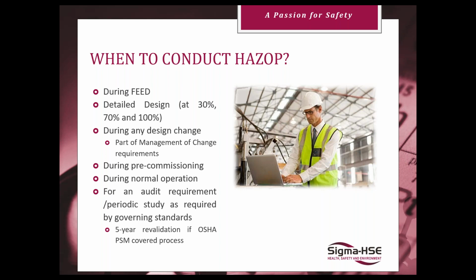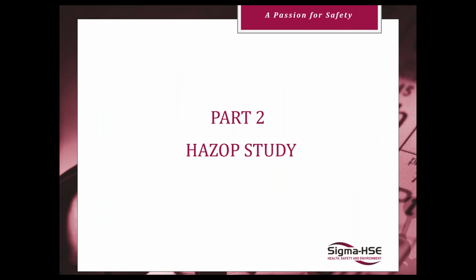Pre-commissioning activities, construction's completed, you're about to start up, perform a HAZOP on your commissioning activities to make sure your commissioning procedures make sense. Normal operation, audit requirement, periodic study is required by governing standards, 5-year revalidation if it's OSHA PSM covered. If a facility has an incident, there may be a directive that they update their HAZOP at a greater frequency than 5 years.